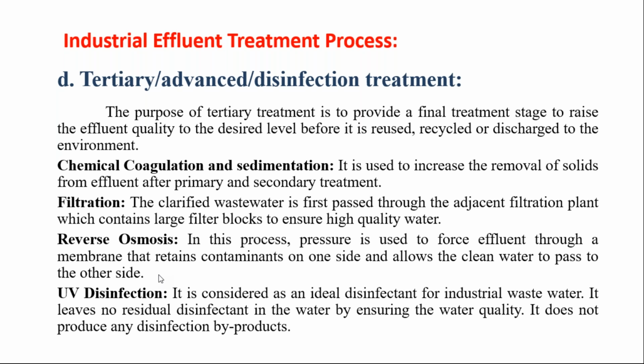The pressure is required to flow this wastewater, and that is why the motor requirement or the pump requirement is there to operate these reverse osmosis facilities. But when total dissolved solids are present in the wastewater, and if you want to remove these total dissolved solids, then this is the best method to use, that is called reverse osmosis.